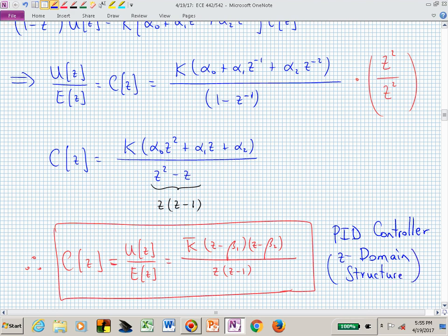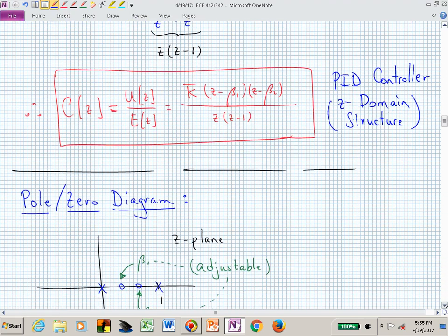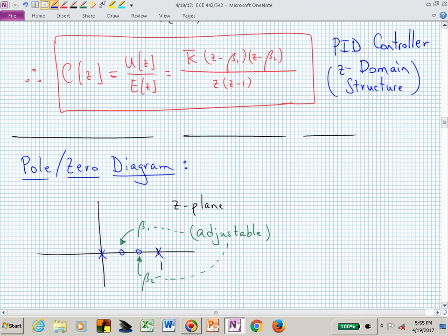In the frequency domain. Or if you wanted to think about that in terms of your shakers, when we're designing controllers, you can now have a zero shaker and a pole shaker, and you want to sprinkle poles and zeros on the complex plane to give you the flexibility that you want to achieve the root locus that will give you the dominant poles that you want.